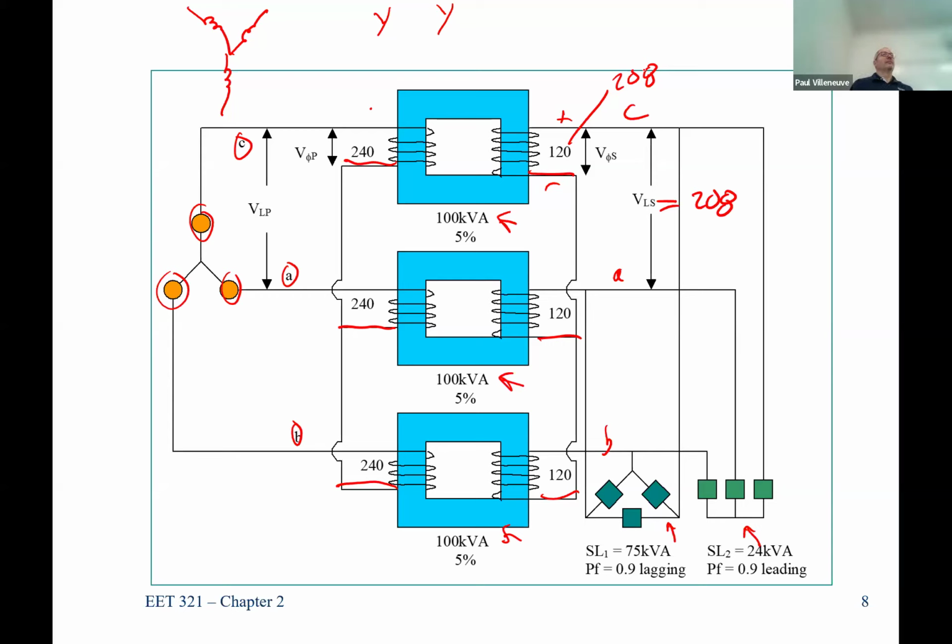Larger. Cooking, well, let's assume that it's a gas. No, it's a pizza place, right? So it's gas, so they don't need a lot of power for that. What would be the power demands? Heating and ventilation, you can get single phase, right? Everybody's house here, you have heating and ventilation. That can be single phase pretty easily, unless it's a huge facility. You're missing one very, very, very important piece that has a tremendous load, surprisingly. Yeah, the dishwasher. Why is the dishwasher such a high load?